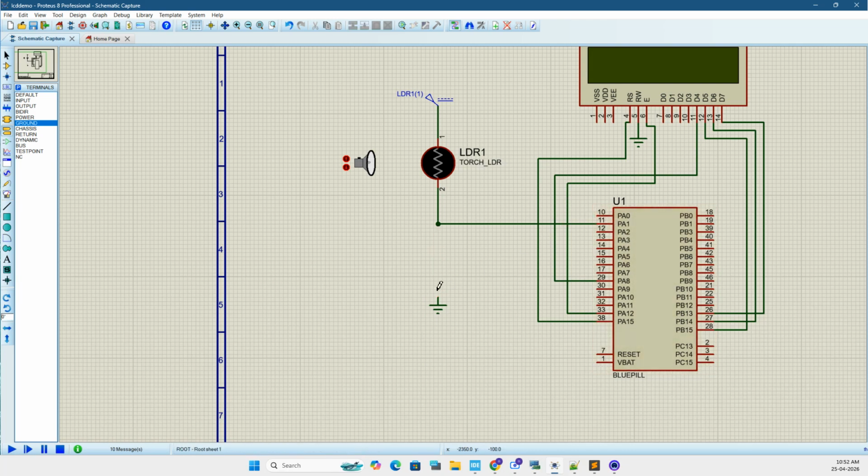Now, I am putting in a resistor. Why am I not doing something like this, providing ground directly? Because whenever you press the switch, VCC is going to follow the least resistant path. It is not going to go towards the controller, it is going to go directly towards the ground. If positive and negative are connected directly by a wire, say you have a battery and you short the positive and negative terminals, it will be a short circuit. To limit that, we are putting one 10K resistor over here. So this is what the pull down resistor is about.